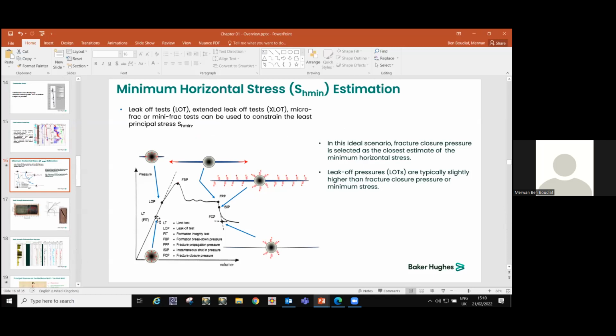But they are not going to initiate any fracture or anything else. They are just saying that, for example, if they are using 2 SG mud weight for the next phase, they will pump pressure around 2.05 SG and see if the formation breaks or not. So this is something just for security that the drillers are doing.